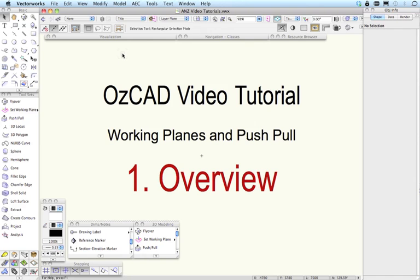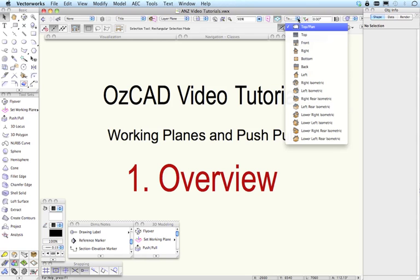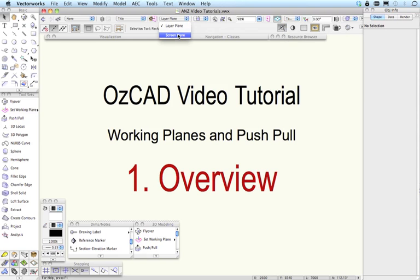If you only work in 2D and never work in 3D, then you really don't have to watch this movie. The only thing I would say to you is, you can leave this set to screen plane if you only work in 2D, and you can always have this set to top plan. If ever Vectorworks starts behaving strangely, it's possibly because you're in a top view or other 3D view instead of your top plan view. So if you only work in 2D, just stick with top plan and have this set to screen plane. Okay, for all the others,